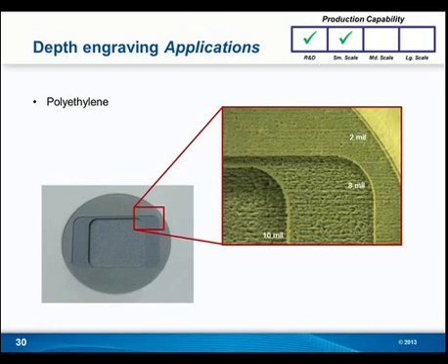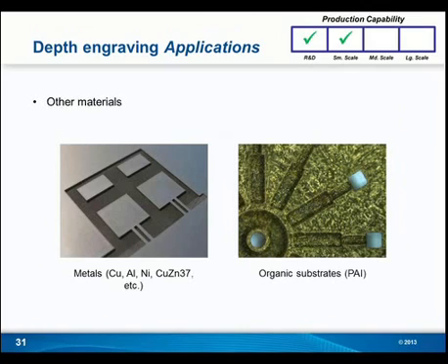Yeah, and to tie into that, I just want to remind everybody, in this case, the pocket creation was only done in one substrate, but you're able to do pocket creation in a multi-layer board as well. So you can remove substrate and then metal and stop at the next layer of substrate, or remove more substrate, stop at the next layer of metal, and so on. And in fact, very recently, I had a customer that did that very thing. That was one of the requirements.